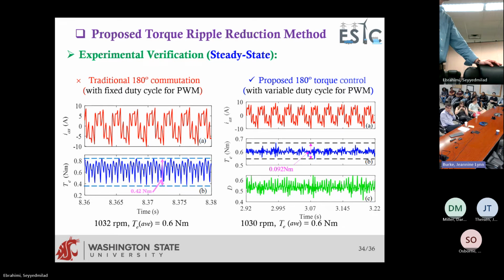Did you look at the effect it had on the position of the motor? Because torque is certainly important, but the end result you'll care about is really going to be the second derivative of these things. I can look at them and say it looks like an improvement, but did you do any analysis on that second derivative to see what that translates to in terms of better exact positioning? No, we haven't done that.